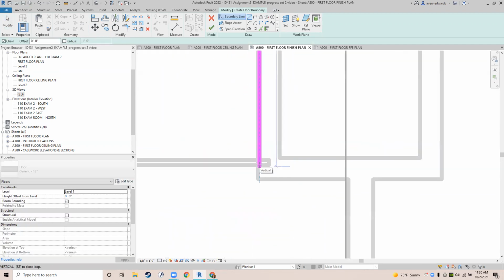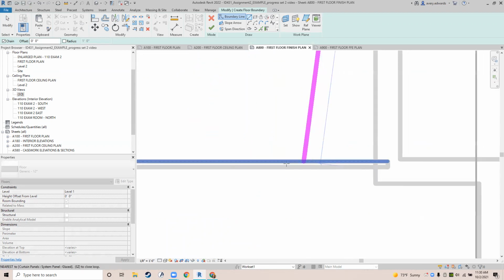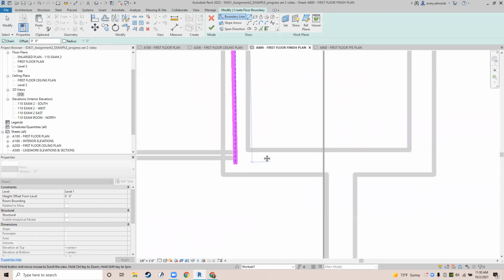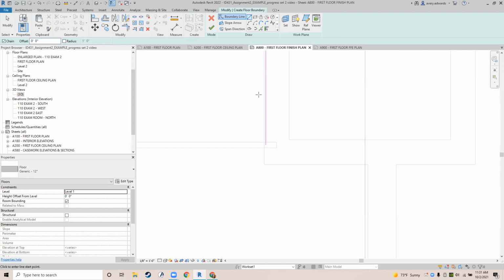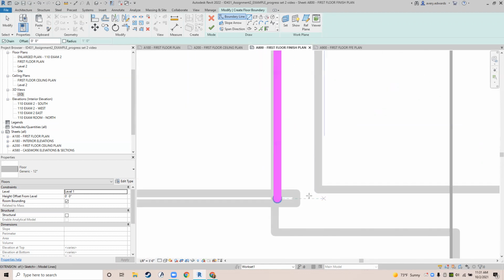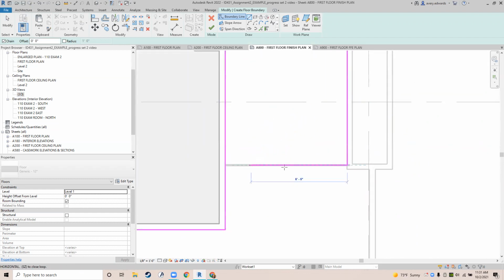Here is another little tip. If you're way zoomed in and you're having a hard time getting a line right because lines get wider as you zoom in, and you have something that's really close but not quite on, you can type TL for thin line, or you can select it at the very top of your screen. There's a wide line and a skinny line with a dash. It will make everything really thin, skinny lines, or you can do it again to make everything go back to normal. Sometimes that's helpful when you just need to see what's going on and you need a skinnier one.